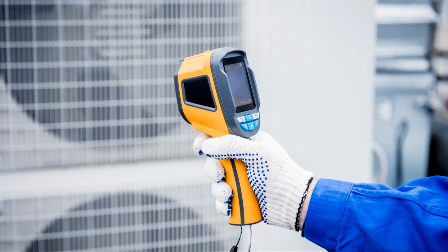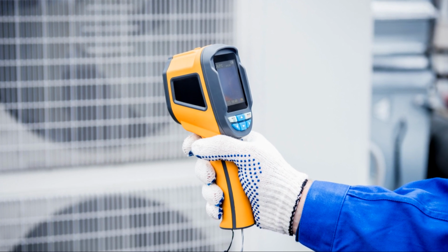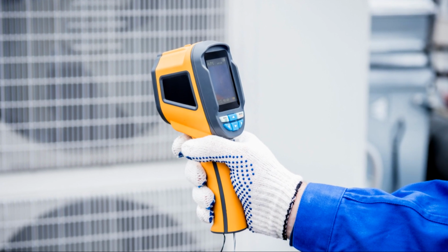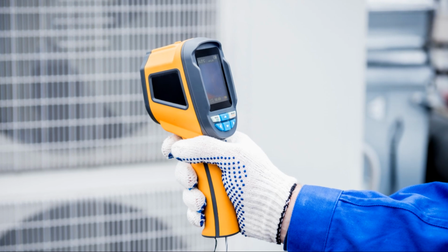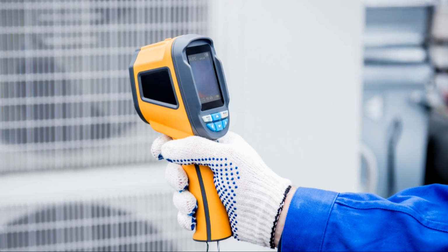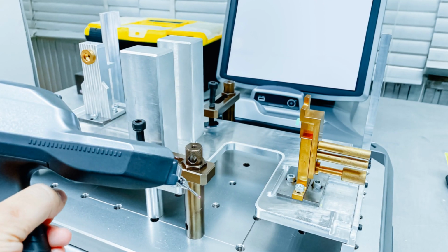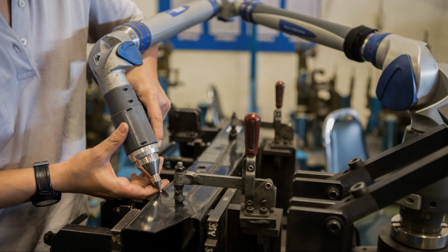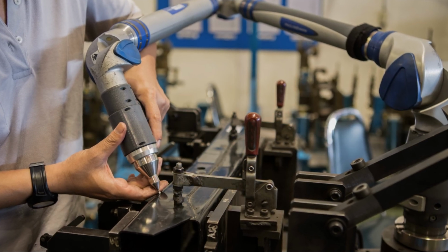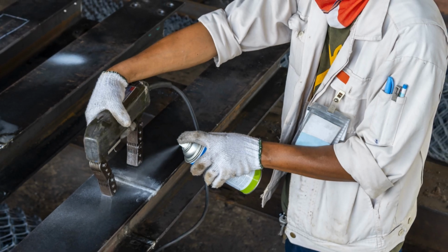Visual inspections uncover contamination, detecting dust, debris, moisture, or chemical buildup that may be insulating heat or accelerating component degradation. Physical damage such as cracks, corrosion, worn insulation, or other mechanical stress indicators that contribute to equipment inefficiencies are revealed during visual inspection of components and parts.